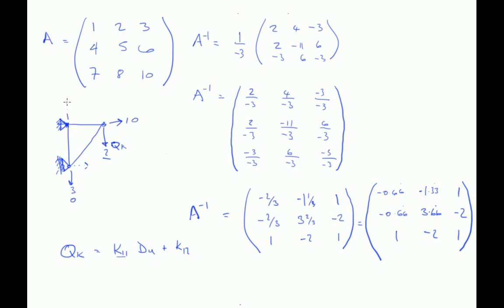Let's draw that way up. So these are fixed, so these have no deflections. So we know the deflections. We also know that the deflections are 0, so these actually cancel out. So we're left with this equation. The force known is the stiffnesses times the deflections unknown.